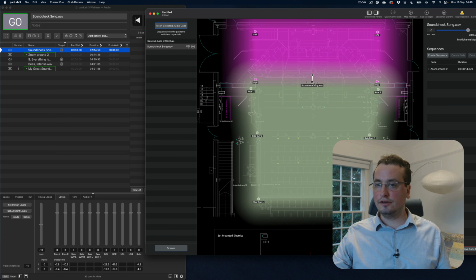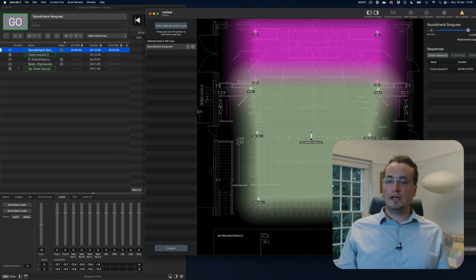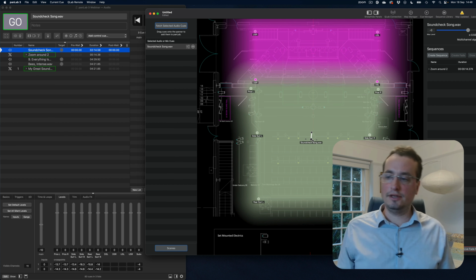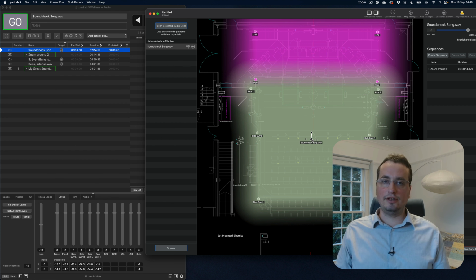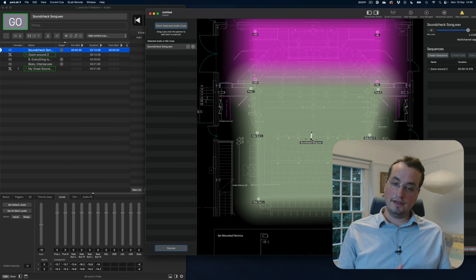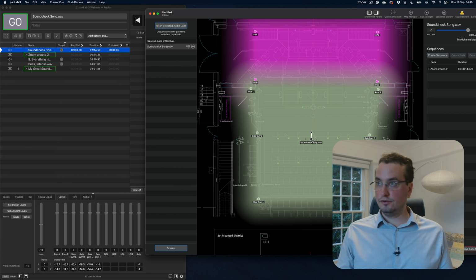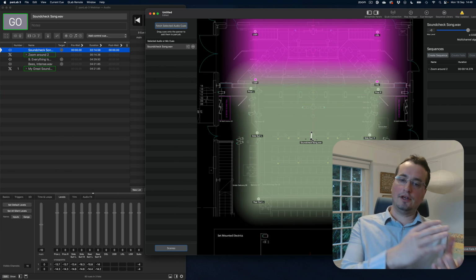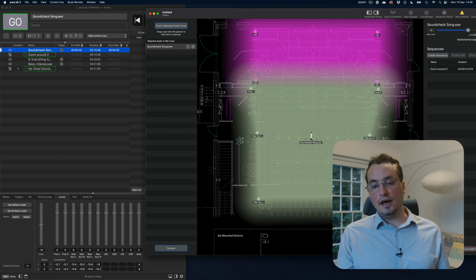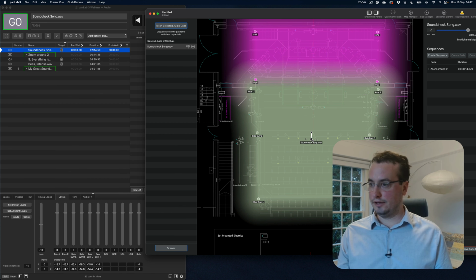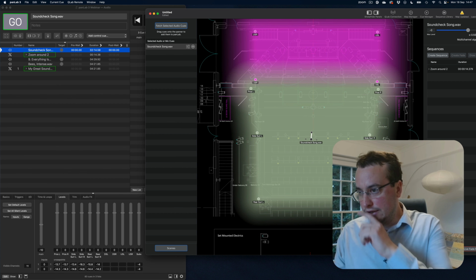So with a zone concept, as I explained before, we're working out for you the relationship between, in this case, the 6 loudspeakers in this zone. So it's doing a similar thing in the sense that both of those examples that you give and this are amplitude-based panning algorithms. And SpaceMap is also like an equal power panning, so they'll try and do the normalization for you as well. But where we're going further in that respect is we're working out, as it's just baked into the algorithm, the relationship between all these loudspeakers for you. But good question.